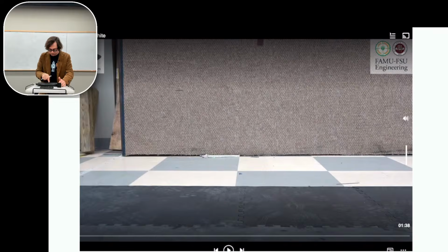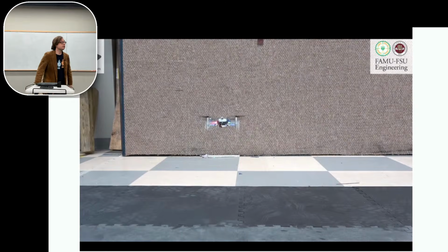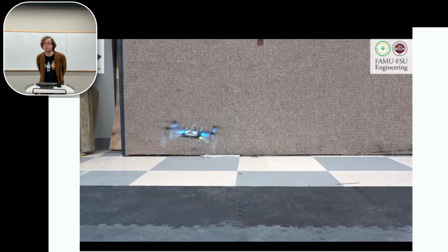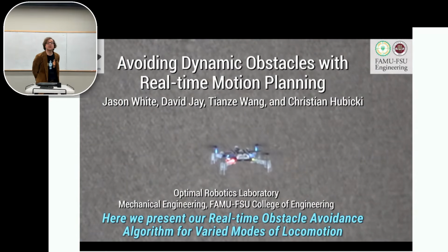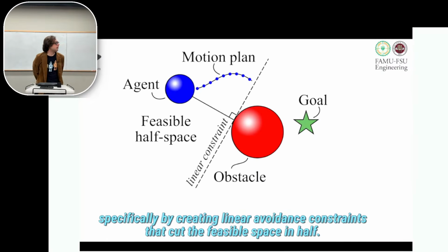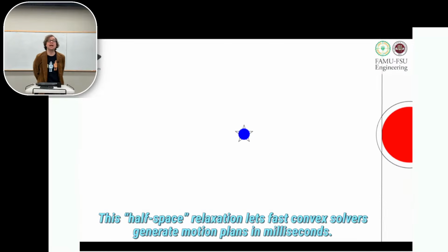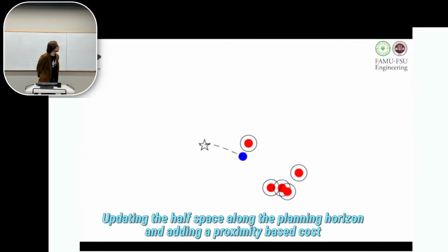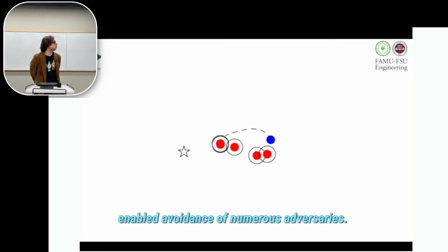Okay. So here's a drone in our laboratory using model predictive control. It's literally doing the example we had here. Instead of the professor being in front of you, it's a little pendulum we had swinging at the drone. We're telling it to stay in the center position. We give it constraints that it can't touch the obstacle. And so the way it does it, we have our own sort of fancy little way of making all the constraints linear in our optimization problem. That's why you're going to see a lot of lines here. Okay? Look, that's that little dashed line. That was the plan. It's always updating. Okay? Look, and because the constraints are linear, you can add tons of linear constraints and it's still convex, which means it still runs pretty darn fast, right?